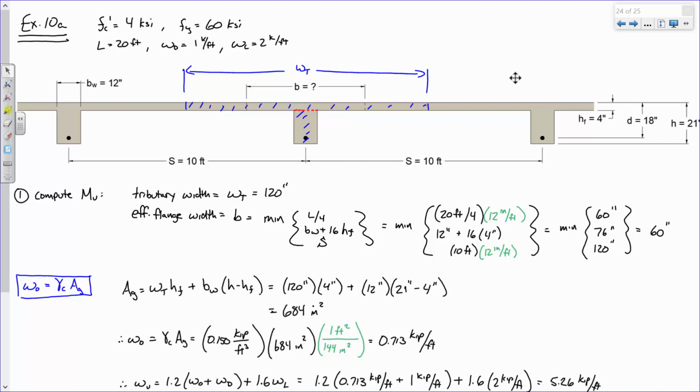Now, one thing to note for your upcoming homework assignment: I gave you the load on the beams in terms of kips per foot, but on the homework, it's a pressure load. So you need to distribute that to the beam, times the tributary width and all that.